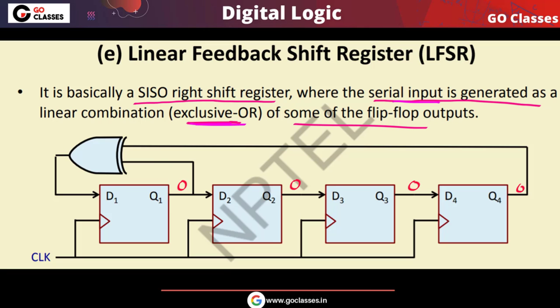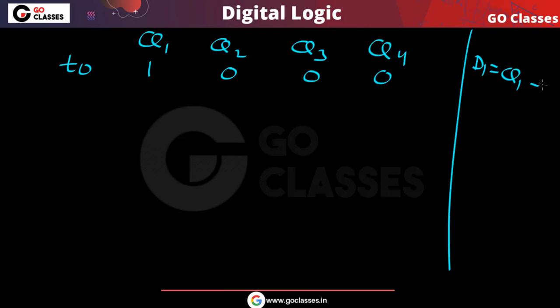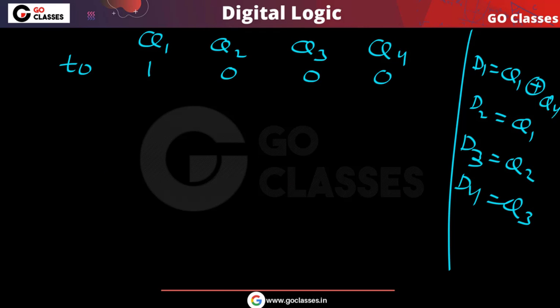Now let me assume that I initialize like this: 1 0 0 0. This is your Q1, Q2, Q3, Q4. At time t equal to 0, this is the initialization. You already know that D1 is equal to Q1 exclusive or Q4, D2 is equal to Q1, D3 is equal to Q2, and D4 is equal to Q3.